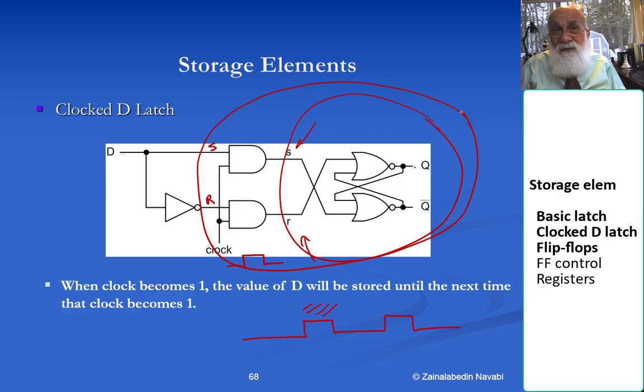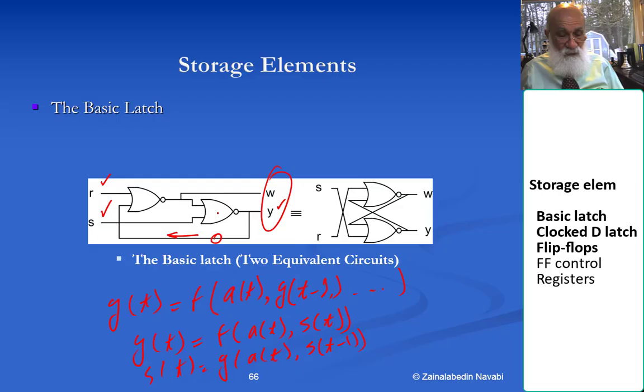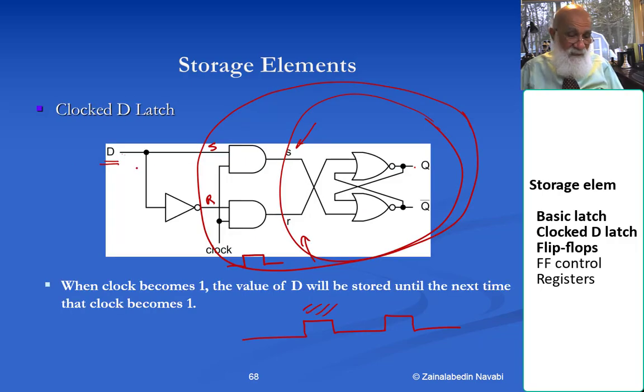in order to make this structure remember some actual data, even a 1-bit data, I like to look at it differently. I'm going to put the data input here on the left, take that into S, and take the complement of it into R. Remember, a few minutes ago I said that the structure here doesn't like simultaneous ones on S and R. On this one, when D is 0, there is a 1 on R. At the time of the clock, a 1 on R resets this.